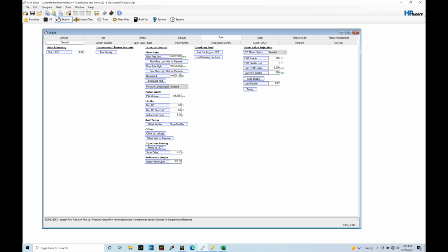Now, the Coyotes are a returnless system, and they operate between 55 to 58 psi, the way that the fuel system is designed. So they are going to be a relatively fixed fuel pressure in the system, but the multipliers here allow the ability to go in and change what the injectors flow based on what the...